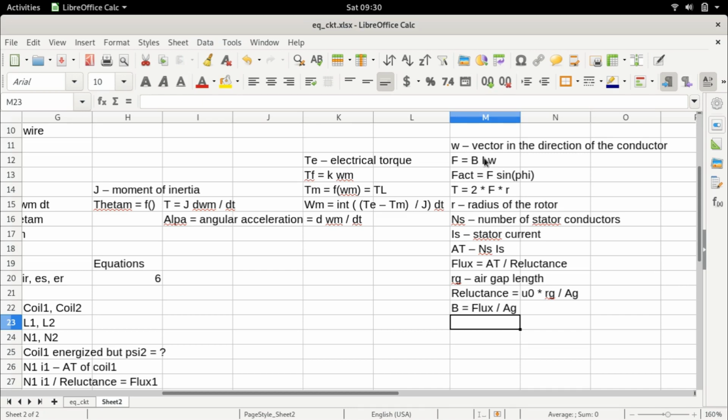I, again, you can calculate it by various ways. You can simulate it as well. But let's say, for example, there was a certain current. In that case, we now know all the parameters that go into calculating the force and therefore into calculating the torque. So this is a way in which we can potentially calculate the torque which is produced by the motor.